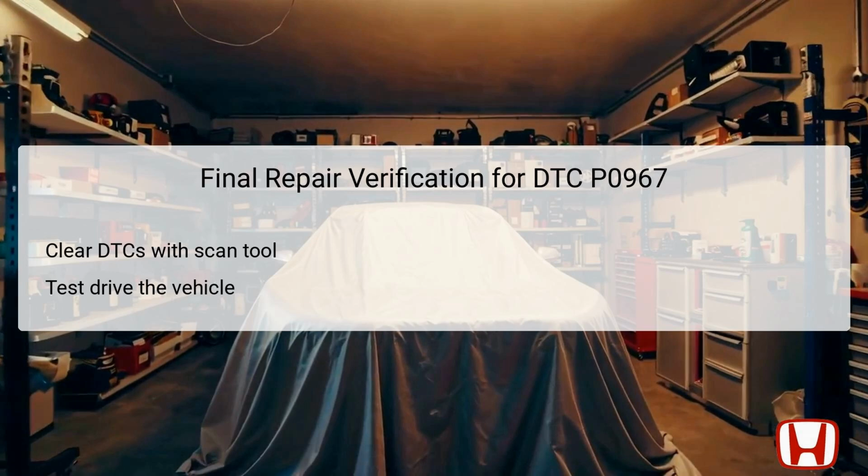Once repairs and replacements have been completed, it is essential to verify that the issue related to DTC P0967 has been resolved. Begin this process by using the scan tool to clear any stored DTCs present in the TCM. This step ensures that the memory is reset and allows for new diagnostic information to be recorded during live operation. After clearing the codes, a test drive should be performed. This drive will help to confirm the vehicle's operational integrity and allow the TCM to run the diagnostic checks.